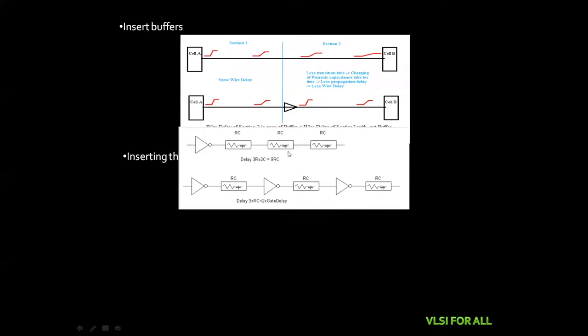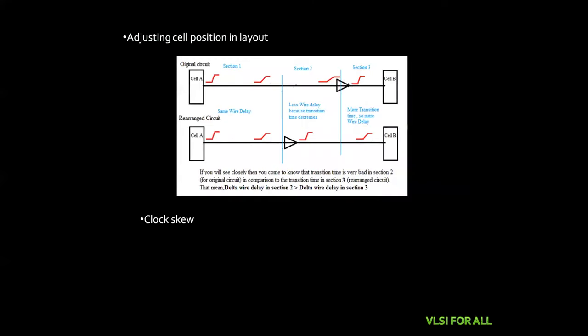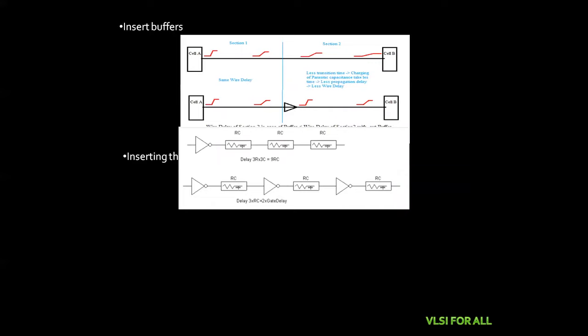And the next one is inserting the buffers. Sometimes we insert the buffers to decrease the overall delay in case of the long wire.